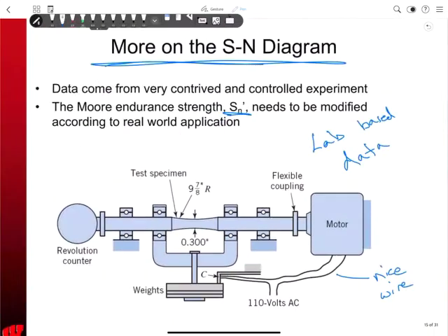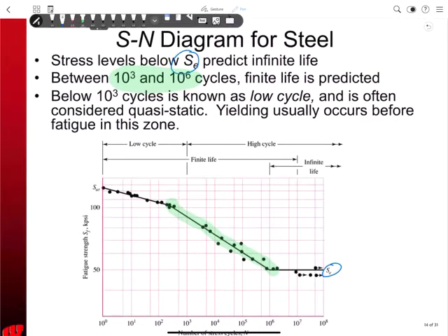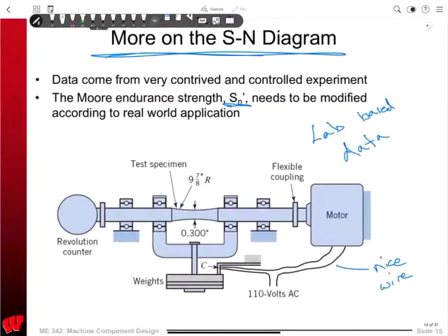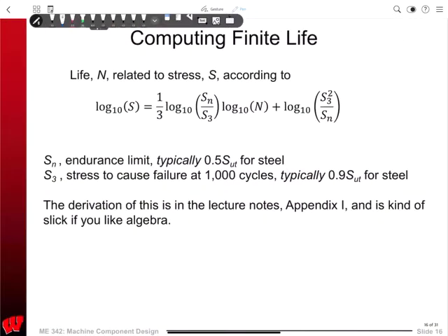So as we mentioned, there's this linear in the green section here, a log linear relationship between the stress and the life, hence the stress life method. Let's slide that up a little bit. So there's the number of stress cycles and then the fatigue strength at that stress, or at that number of cycles. So that's log linear. This is really just y equals mx plus b. Let's write that in blue still. So this is just y equals mx plus b,